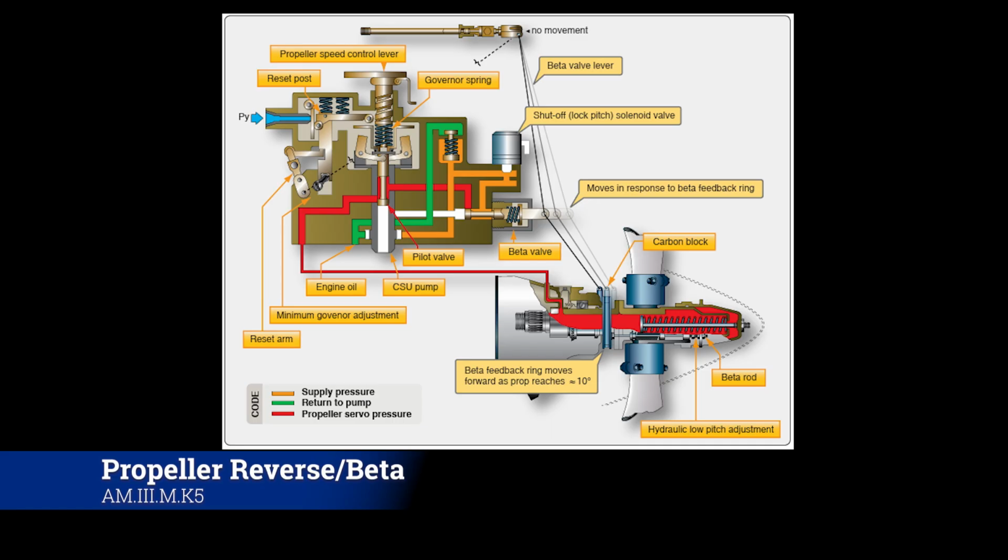Now, the solenoid is energized by a switch mechanically connected to the propeller slip ring linkage via a second carbon block. As the oil pressure leaks off around the propeller shaft oil transfer sleeve, the blade angle slowly drifts back towards high pitch. This deactivates the low pitch solenoid valve and restores the oil supply to the propeller servo. The low-pitch solenoid valve cycles closed and open as a backup to the valve function.